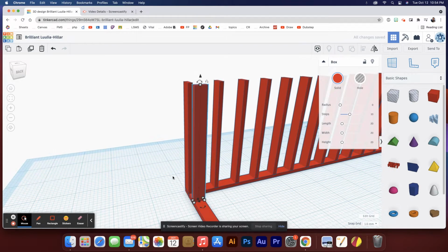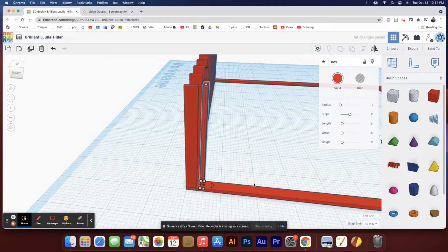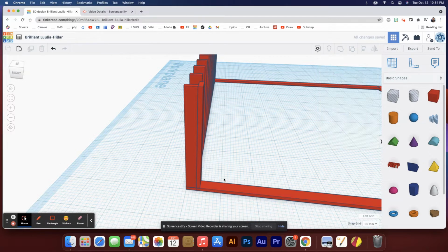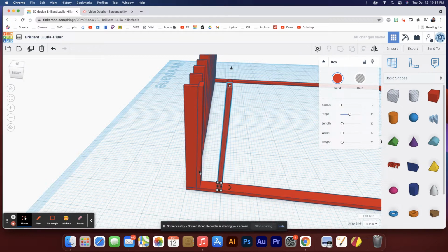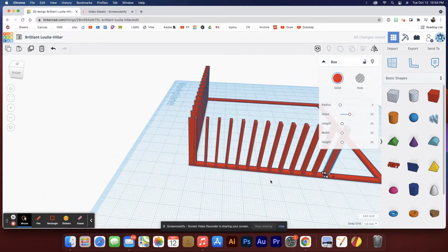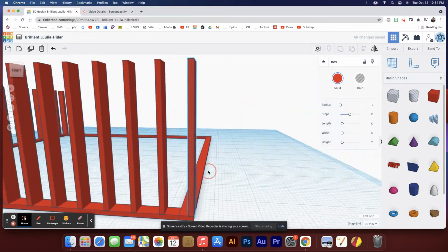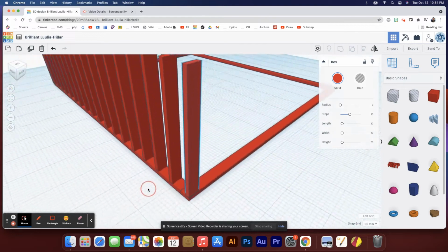And then I'm going to right arrow it over. And let's see, maybe I'll just park it right next to that. And then I'll Control D, and then I'll right arrow. Oops, nope, that's not what I wanted. I want this selected. Control D, right arrow. And then we'll go Control D until it makes it to the end. And let's zoom in by hitting F. Looks like we ended up perfectly right on the end like that.